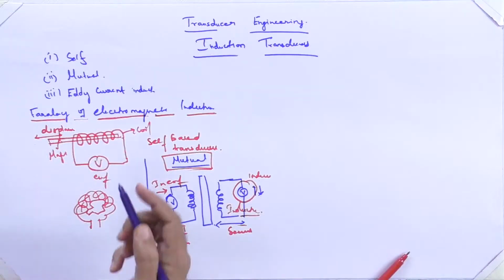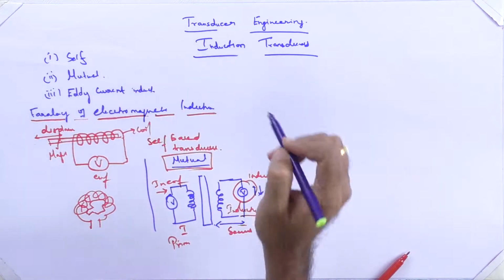transducers also. You have to recall what the resistance based transducers are that we have seen for linear and angular displacement measurements. Those are, first, the linear potentiometer or translational potentiometer for the linear displacement measurement, and the rotational potentiometer or helical potentiometer for the angular displacement measurements. Recall these two things and then compare them with these induction based transducers. Here we use it for the self and the mutual inductance.